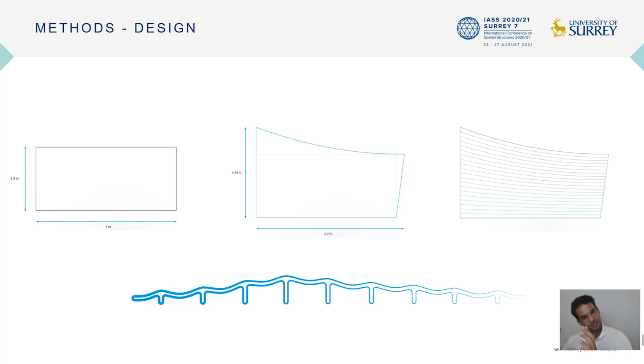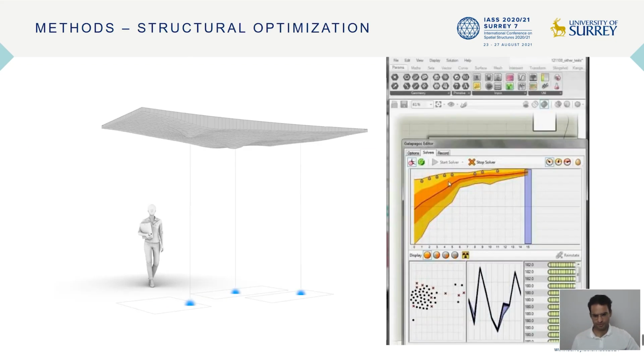So we took a very simple geometry, which is a rectangle. You can see one very simple module of a slab, maybe 4 by 2 meters, which is a prefab maybe. And we also wanted to look at a bit of the design, so we're playing with the inclination as we print along. So we print this actually vertically up, so it's all one piece and one go. And playing with the speeds and the material distribution, you can also create interesting three-dimensional variations of the form, like here the inclination, as you can see, as we go upwards.